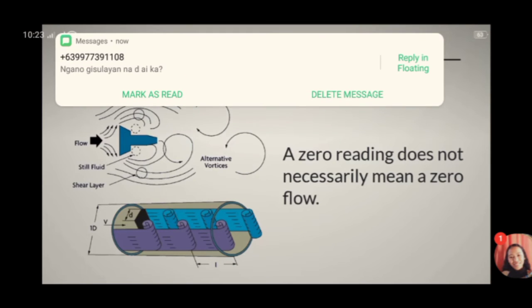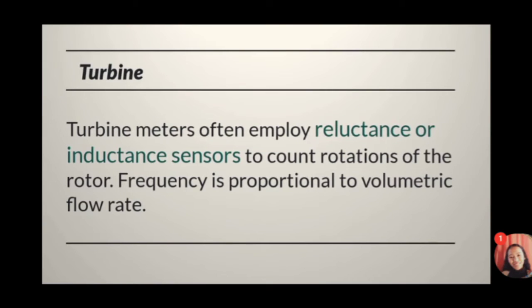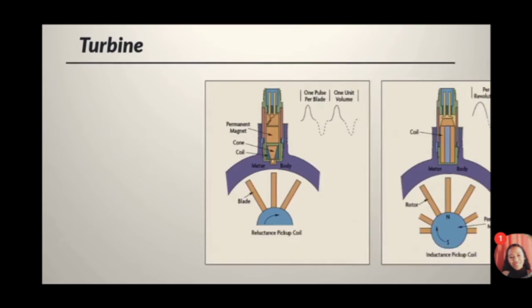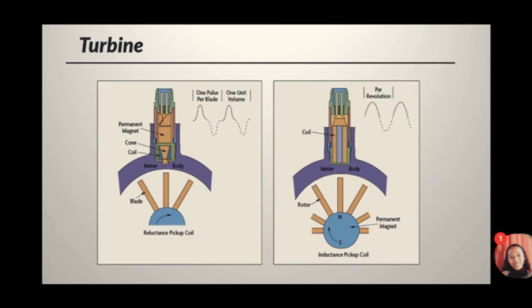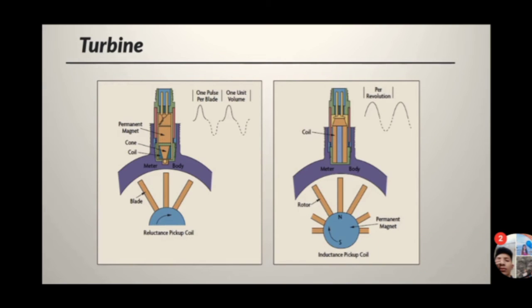The turbine flow meter consists of a multi-bladed rotor mounted at right angles to the flow and suspended in the fluid stream on a free-running bearing. The diameter of the rotor is very slightly less than the inside diameter of the metering chamber, and its speed of rotation is proportional to the volumetric flow rate. Turbine rotation is detected by solid-state devices or mechanical sensors.